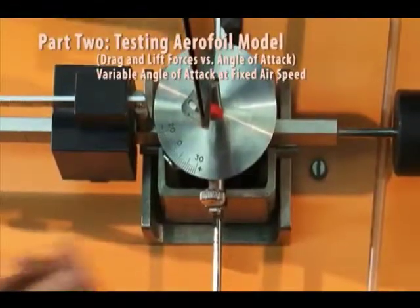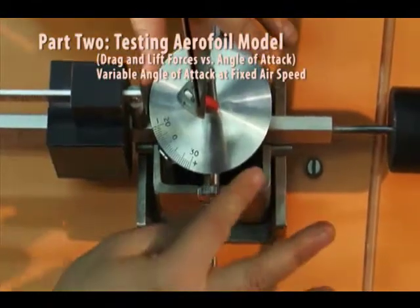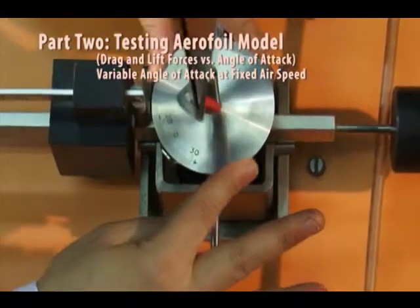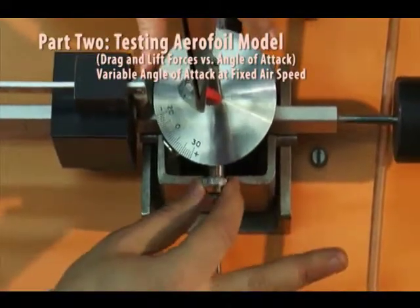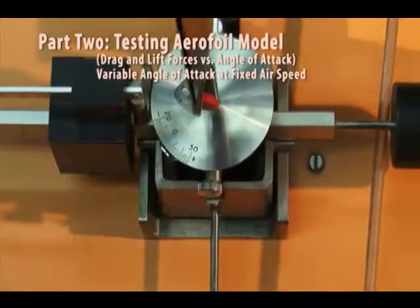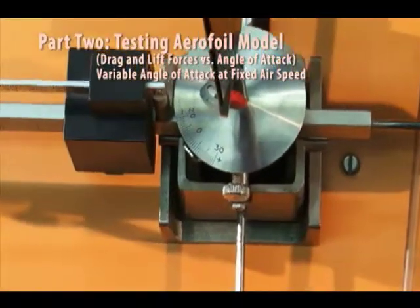Drag and lift forces data are to be collected with different angles of attack. The angle of attack should be increased from 0 degrees to 30 degrees at constant increments of 2 degrees by turning the protractor on top of the balance.